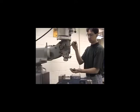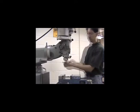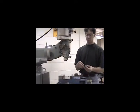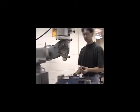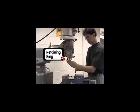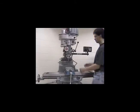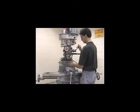A mill is held in place in the quill by a collet. The collet should be chosen to be as close to the diameter of the end mill as possible, while still permitting the end mill to slide freely in the collet. The collet is held in place on the quill by a threaded retaining ring. Use extreme care when inserting or removing the end mill from the collet. If the end mill slips and falls against the table, it will likely chip and be rendered useless.